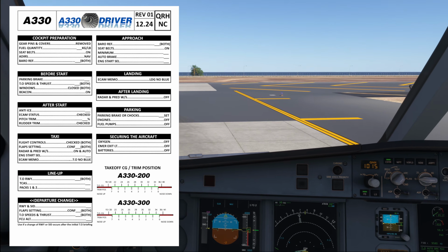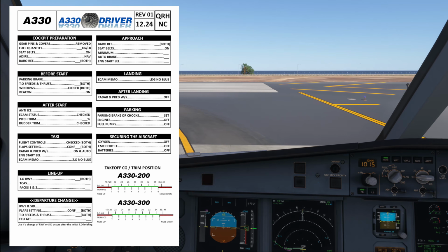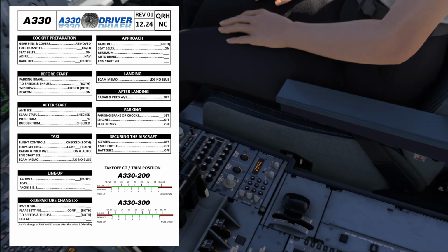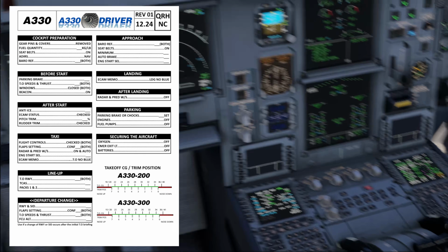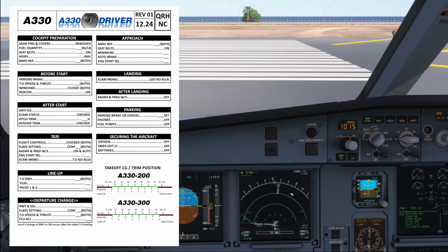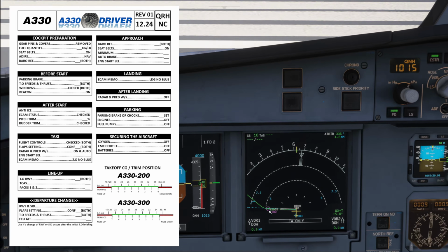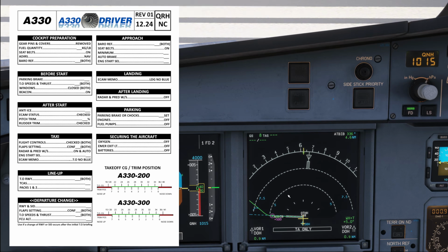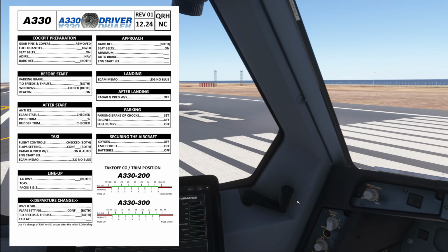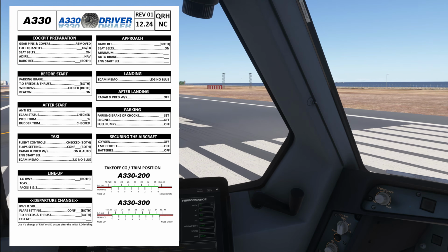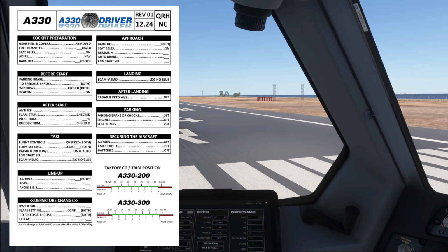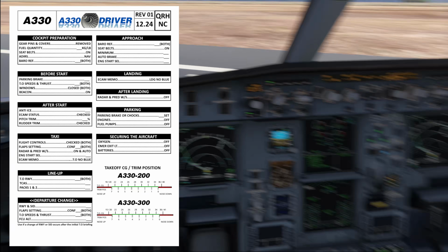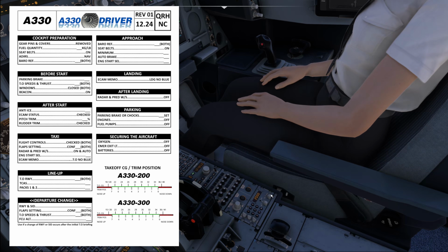The next item is going to be the TCAS, and for this the pilot flying checks the TCAS mode selector. Now you can do that down here and verify that it is indeed in the TA/RA position, or you can look at your nav display, and on here you can see that the lines on the 2.5 mile ring have changed into a different layout, and this also indicates to you that the TCAS is indeed operating. Now the correct answer is either TA only or TA/RA, depending on what is selected down here on the TCAS mode selector.